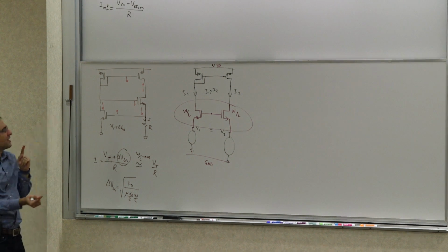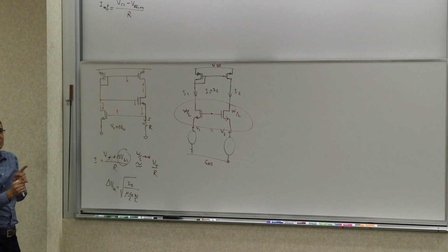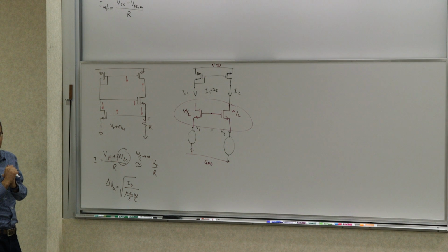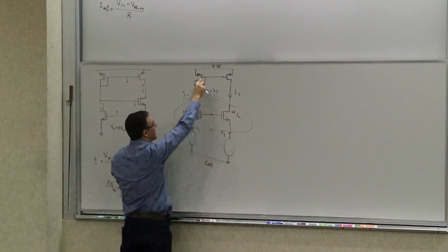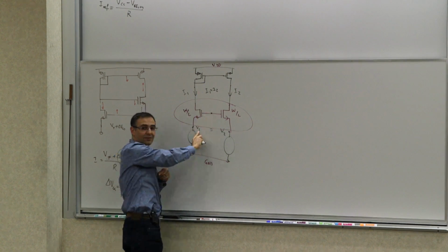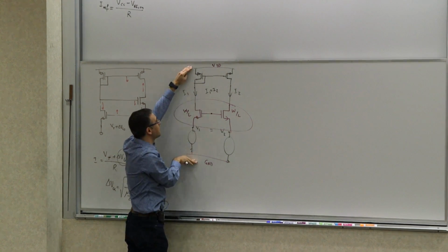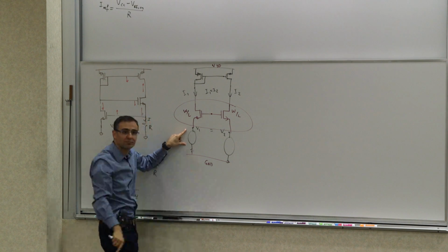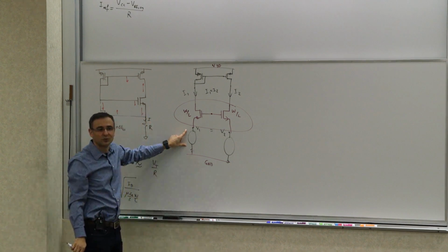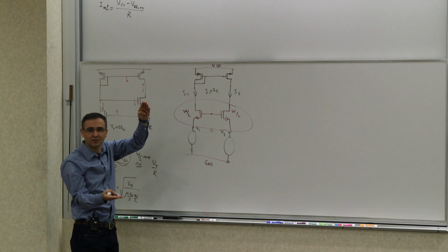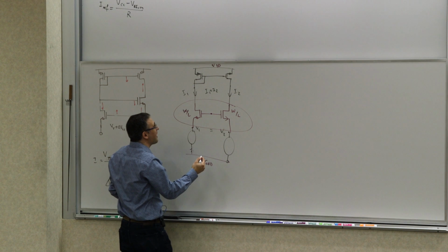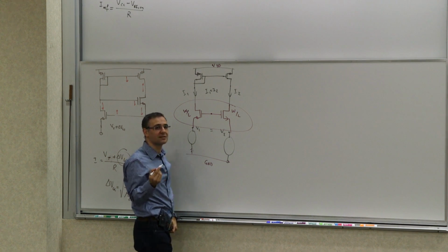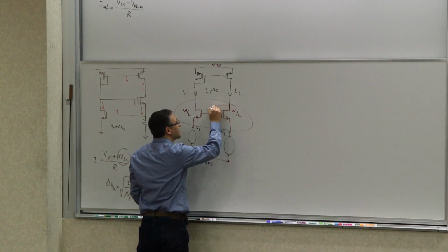So there's one side that, if I put this on, would create that kind of pathway. And there's another side that doesn't. Do you agree that if I were to put this diode connected here, and I have a diode connected here, and whatever I have here, whatever voltage I apply would appear across 2 diode connectors and whatever I put here? So that would dictate the current. There's no floatation. There's no separation. There's no isolation. For isolation to happen, you need to have at least one side be high impedance. And that's why you put it on this side.